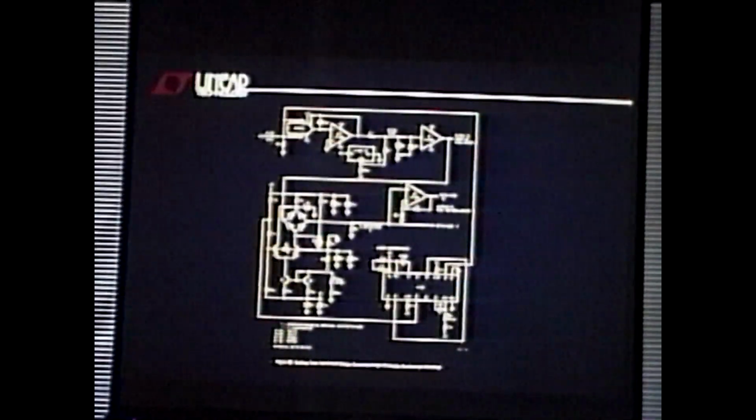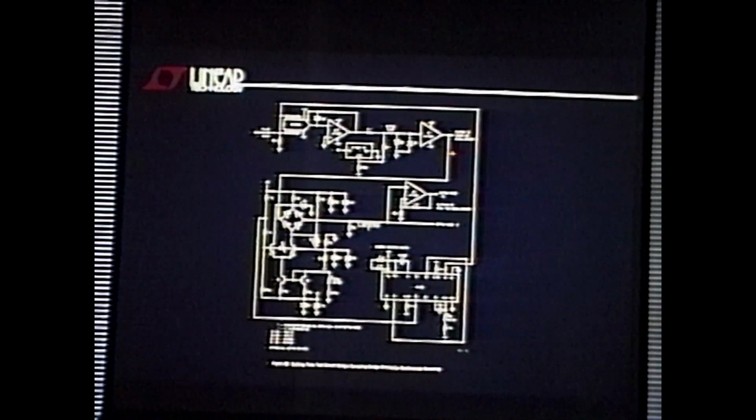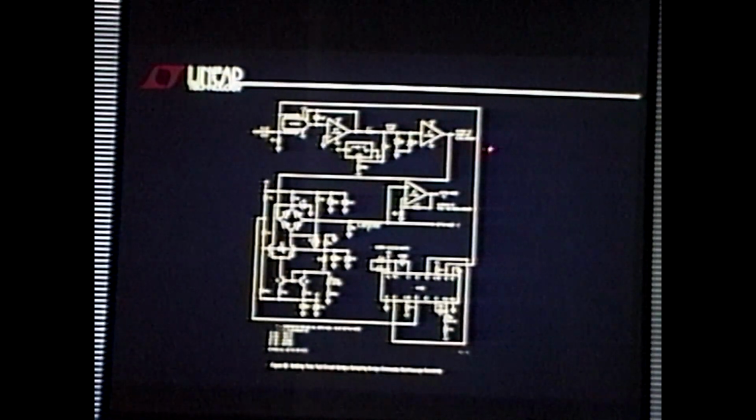You'll notice something else here. There's a port here, it's hard to read, but there's another output indicated. It says output to sampling oscilloscope. What that means is if I've got an old-fashioned 1960s era no fooling sampling scope, this circuitry's already there, so I don't have to build that. If I've got one of those, like an old Tek 661 or a Tektronix 1S1 plug-in for 500 series stuff, I can just hang it right there. I'll just trigger the scope off the one shot.